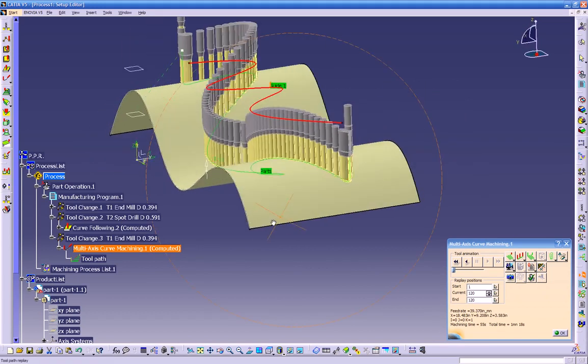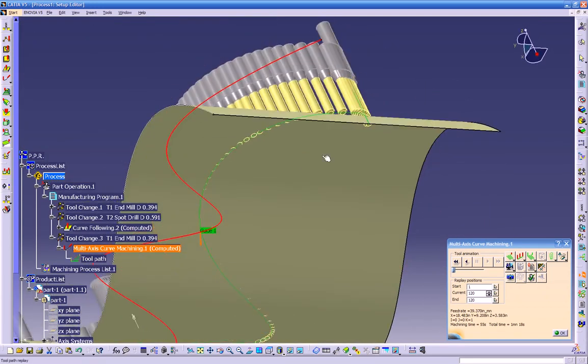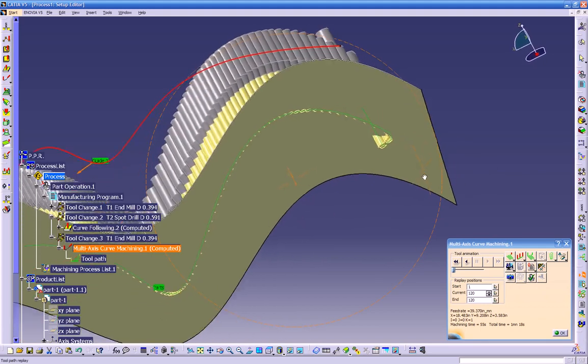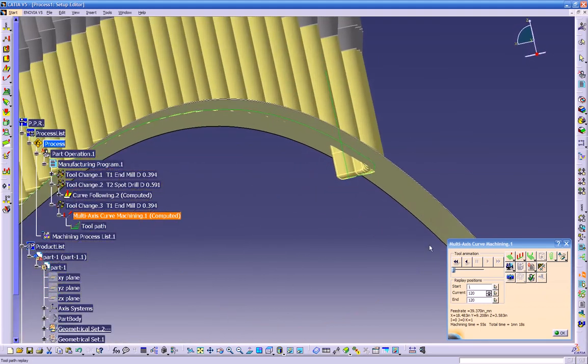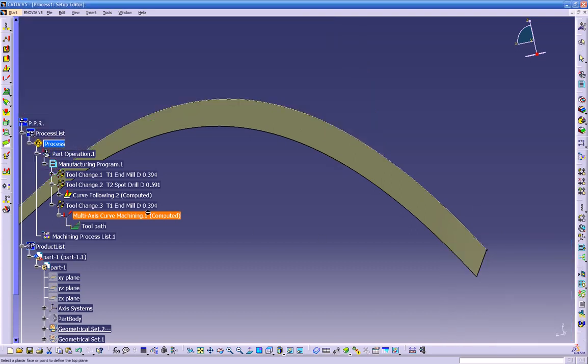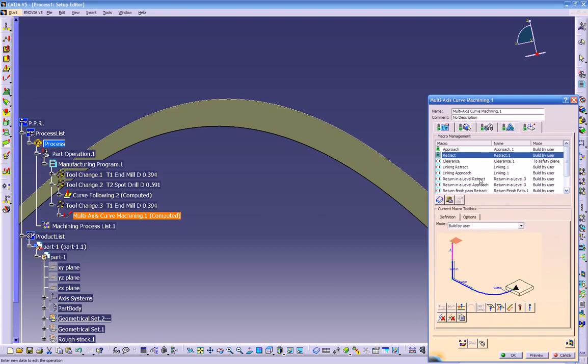Oh, this is not good. Yeah, so the lead in and lead out, it didn't care that I'm using a surface. So yeah, it doesn't work. Let's just turn it off. Let's turn this off because it doesn't like that option. Let's put none.